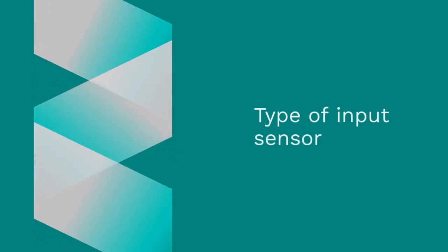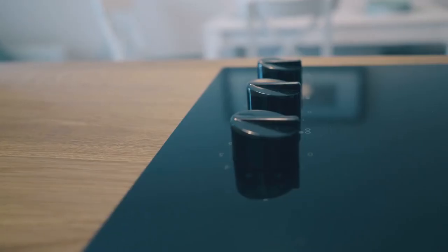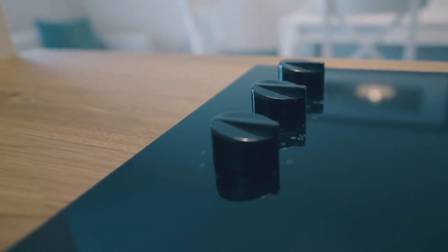Type of input sensor. Not all controllers support all types of inputs like RTD, thermocouple, PT100, PT1000, or NTC. Depending on what type you have, choose the controller which will support that sensor.